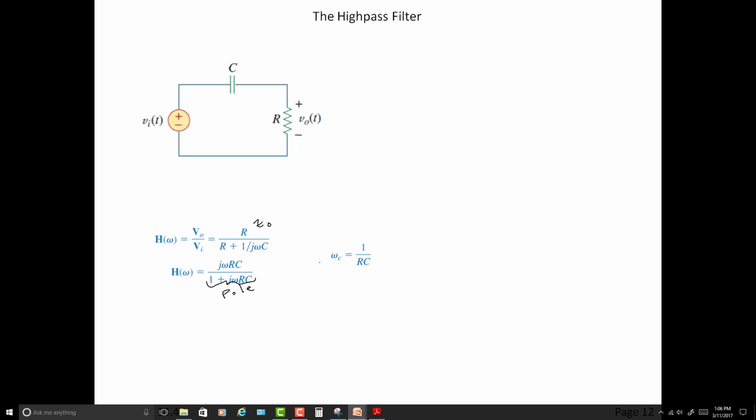The 0 is going to force us to have low response at low frequencies, right? So this is what we actually get out of this picture. You can see it here. Here's our 0 taking place. The 0 is affecting that. And as frequency gets high, the magnitude approaches 1, right? Because now the pole swamps the 1, and you just end up with j omega c over this, and so you've got just 1. That's what it's always going to head for.